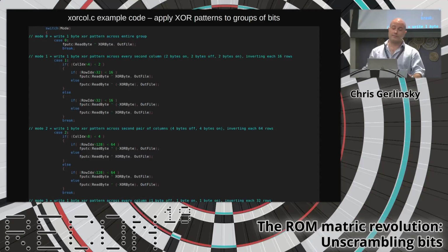So looking at the patterns, in this case, I did have some plain text available from some of these chips. These ST19 smart cards are used in a variety of systems, and some of them have been exploited in other methods, for example, glitching to extract code. So for some versions of these chips, I had pieces of plain text code, and by comparing the plain text code to these visual patterns, I wrote a program that all I'm doing is reversing the visual patterns that I see. I didn't actually fundamentally understand the process that they were using for the scramble.